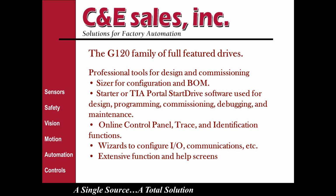Both Starter and Portal Start Drive have trace functions, control panels, and identification functions that are very useful in commissioning the drives and in debugging problems with drives. You can go online with your laptop or PC, monitor the conditions of the drive.